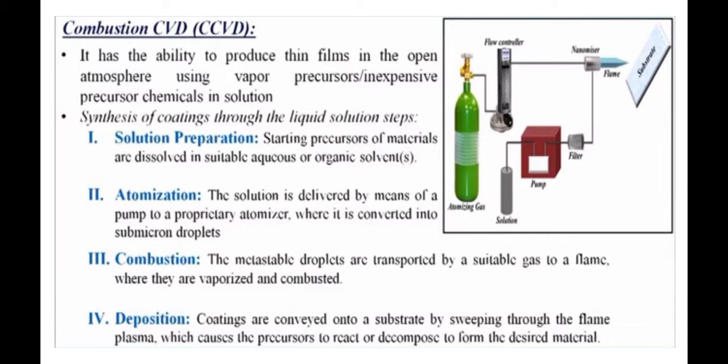The solution is delivered by means of a pump to a proprietary atomizer where it is converted into submicron droplets. Here we give a high force of gas, so the solution in liquid form comes into small droplet form, and then it goes through the flame, giving a certain kind of combustion at that juncture, and the film falls directly onto the substrate and makes a coating there.